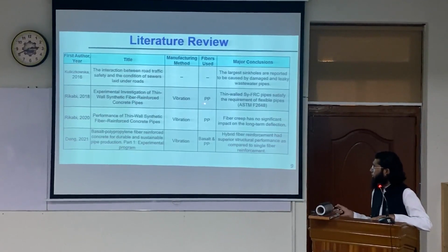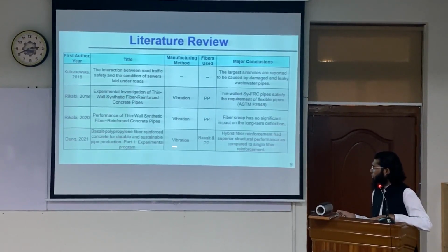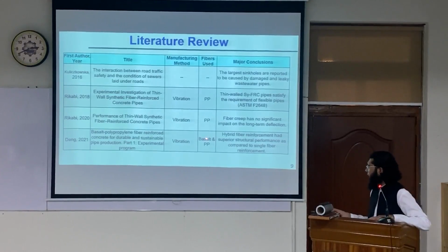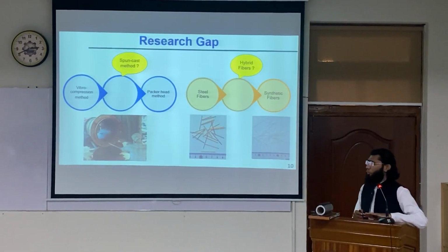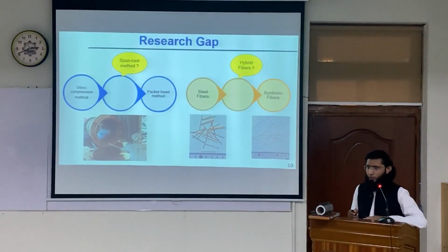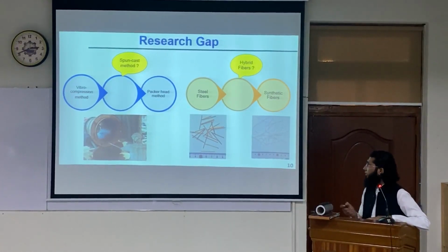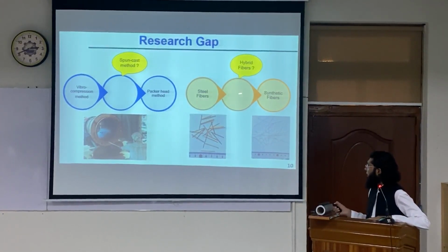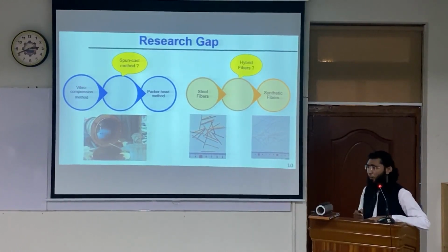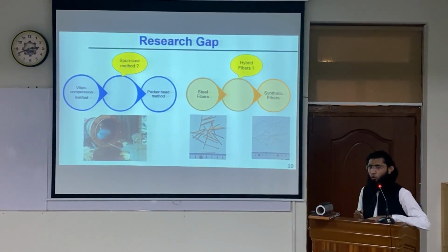Some more studies incorporated PP fibers, and then one more study on hybrid fibers, but the fibers used are basalt and PP fibers. Now, based on the literature review, we came to see that the previous studies have focused largely on either the vibro-compression method or the packerhead method, and the spun cast method is rarely explored. Moreover, these hybrid fibers are not explored in detail, especially the combination of steel and synthetic fibers. So this study is aimed at the structural performance of spun cast hybrid fiber reinforced concrete pipes.